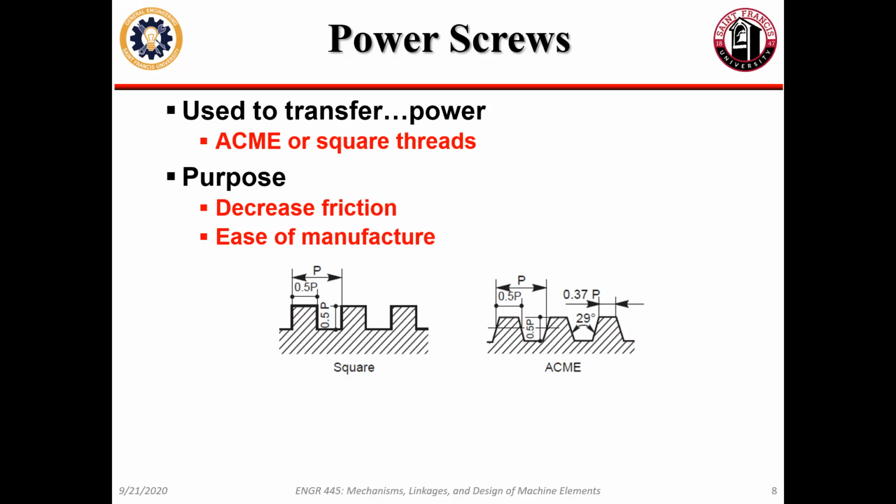This is because an Acme thread is angled a bit, so you have a bit of a wedge. You guys remember when we played with the lathe center? The only thing holding the tool in the lathe center was a wedge. If I just let it sit there, I can pull it back out easily. As soon as I gave it the least tap, as soon as I pushed those two wedges together, you couldn't pull them apart anymore, not without tools. As you might imagine, that's not a desirable quality of a screw. You want to be able to turn those screws, right?